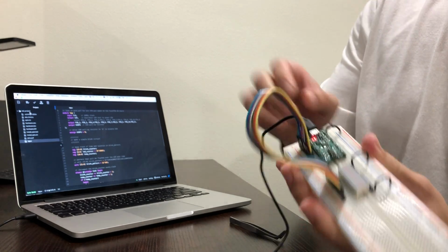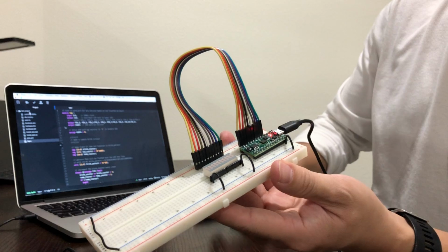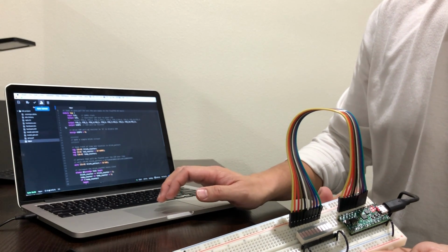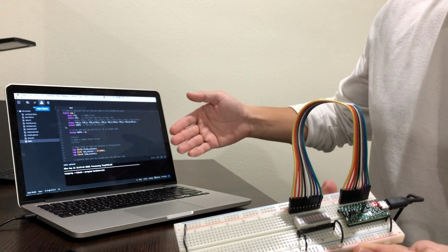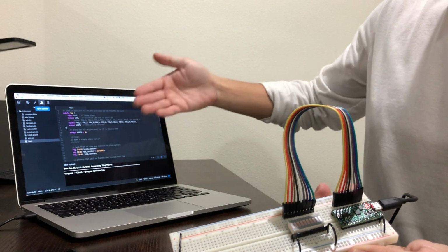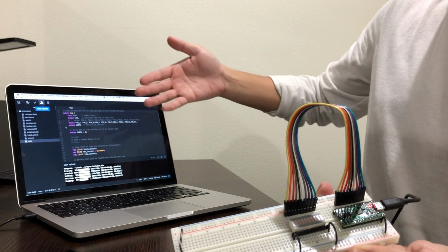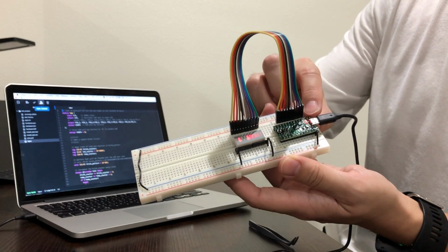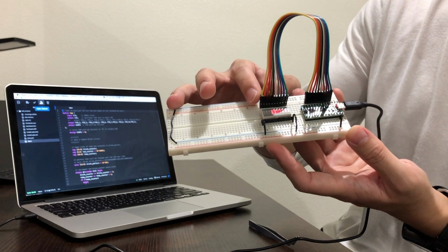When I connect the FPGA board with the computer through this USB cable, I can go to Atom over there and click Upload. Then Atom IDE is gonna check the syntax, compile the code, generate the bitstream, and then download it into FPGA. So basically, we achieved the goal of programming this FPGA.